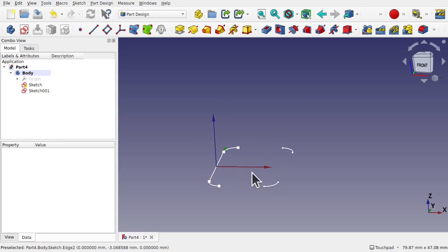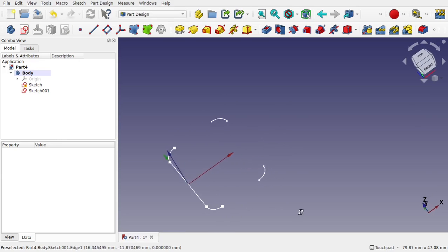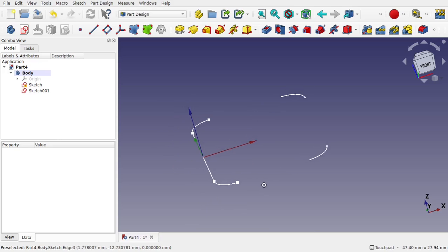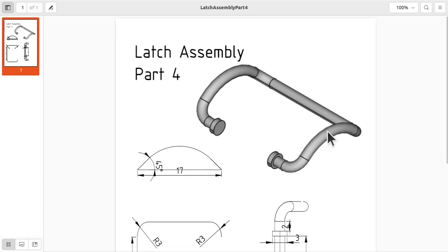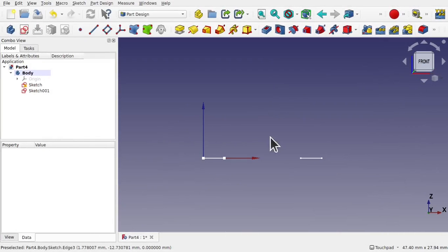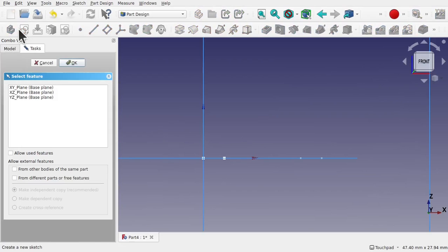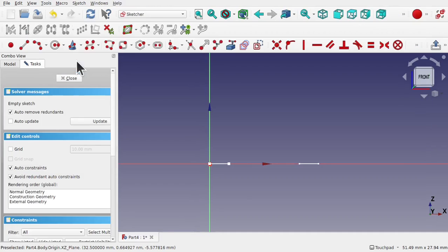So I'm going to create a new sketch for the arc that goes this way. And we're going to pull these in as tangent constraints. So all we're doing is creating this arc here, not this section or this section, because those are being created with our other sketches. And then creating tangency with this arc as a projected line. So when we use the import geometry, we import that arc in. So looking from the front, we create a new sketch along the XZ plane, and OK.